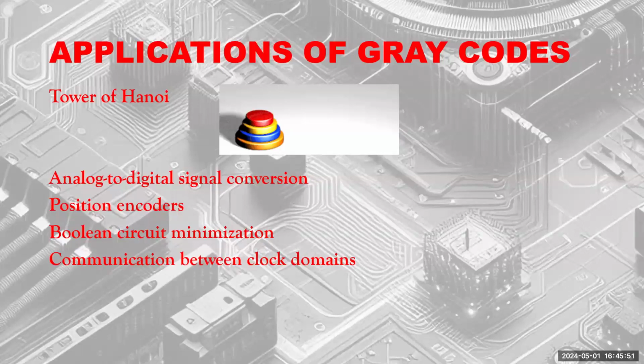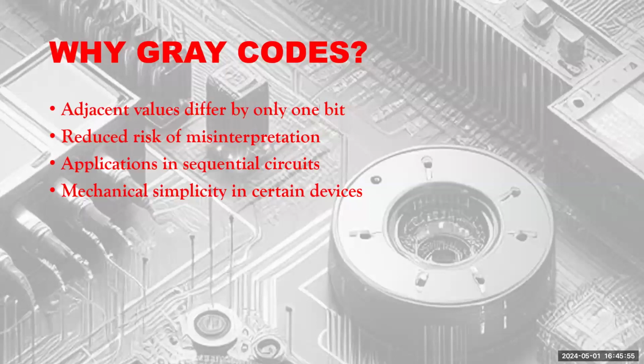Superb. Just one point I want to add to the advantage list. You have outlined very well. The additional advantage is that in a gray code there is only one bit changing at any transition time. So the total energy expenditure is fixed to one change, whereas in a binary code, for example, if the code is moving from FF back to 00, let's take an 8-bit binary code, it moves from FF back to 00.